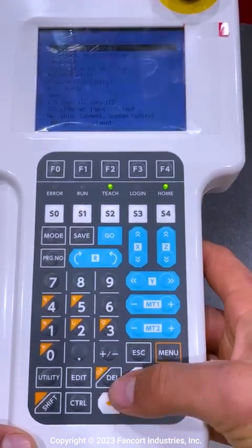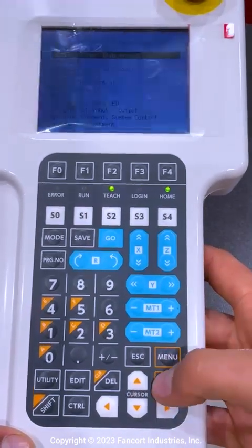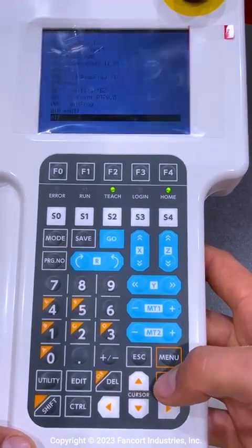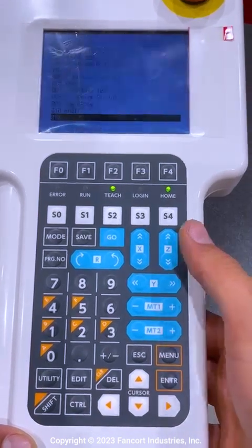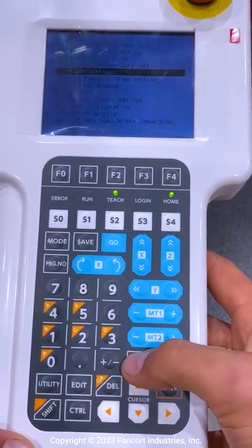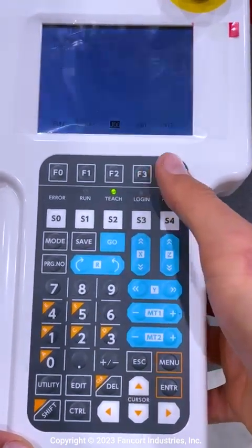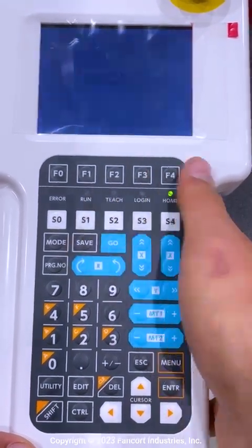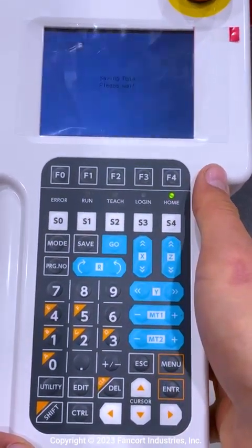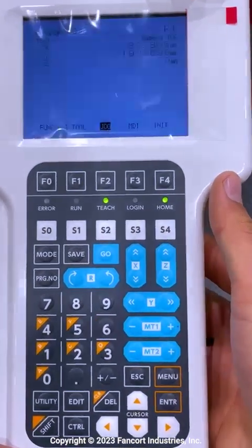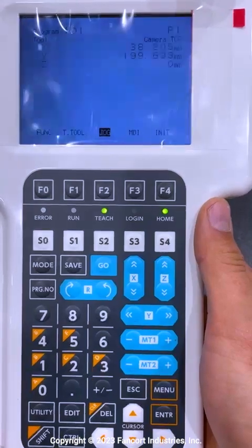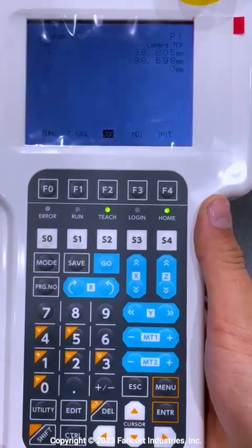Now last, we're gonna go to if branch, enter, and end if, enter. And now we're gonna hit escape twice, and we're gonna save right there. So now it's gonna save everything. And there we go. That's how we create point job 11 in program 101.